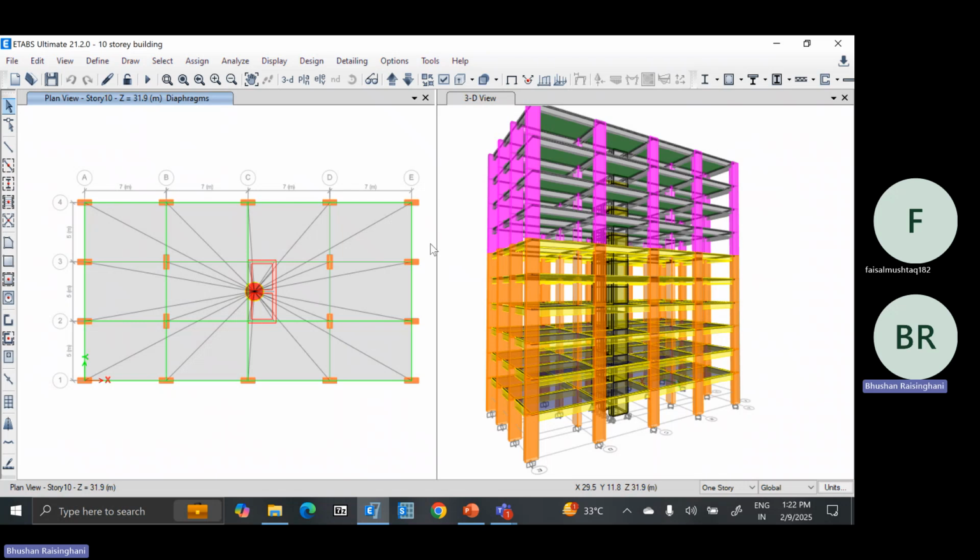So you can depend on auto meshing and choose accordingly. You can choose 2 by 2 or 1 by 1 meshing, or you can depend on the auto meshing tool option of the ETABS software as long as the geometry is not complex. For routine cases, like shear walls and slabs, it is very well to be used. It is okay to directly use it for buildings.